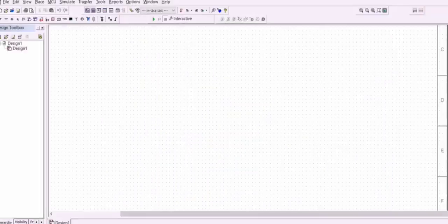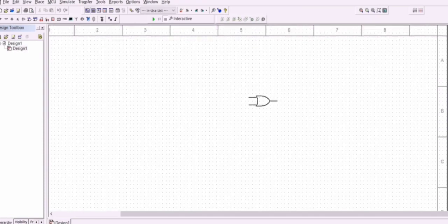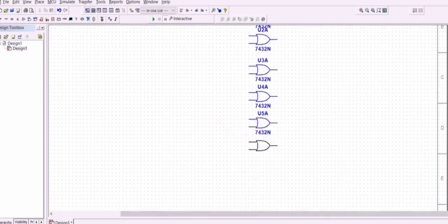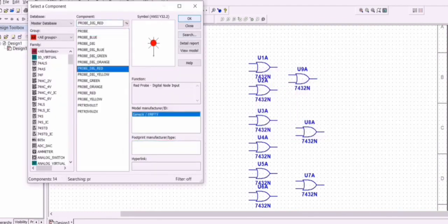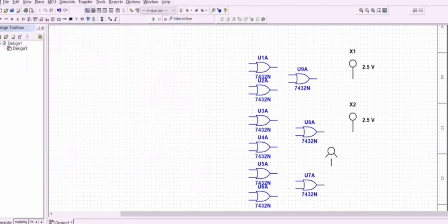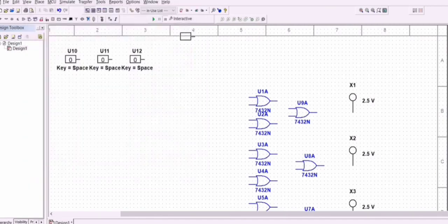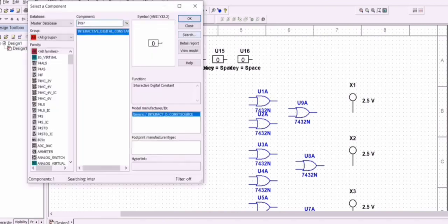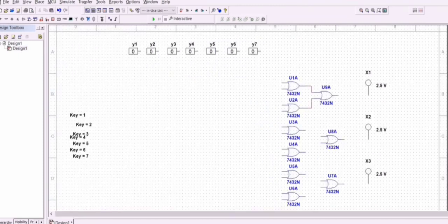This is a logic diagram. Actually, an encoder is a simple circuit or a transducer that converts binary information, which is in the form of 2 to the power n input lines, into n output lines, which represent the n bit code for the input. In the encoder, the feedback signals will determine the position, count, speed, and direction, and the other control devices are used to send the command to the particular functions. Generally, the encoder is considered on the transmitter side, whereas the decoder is considered on the receiver side.